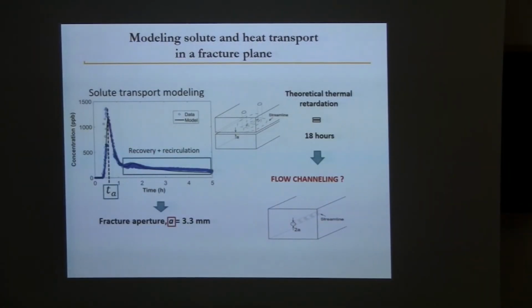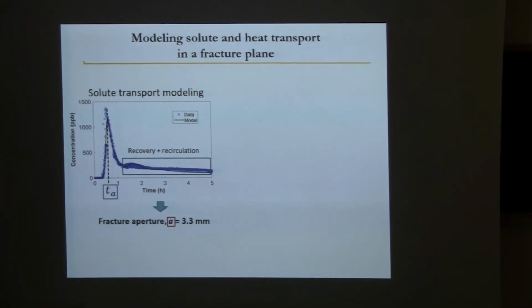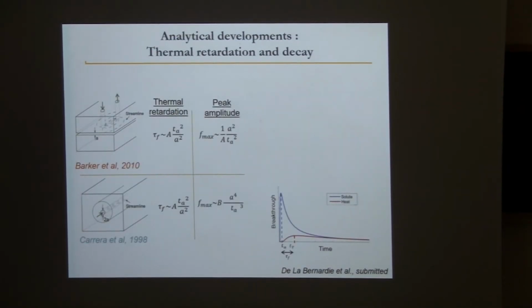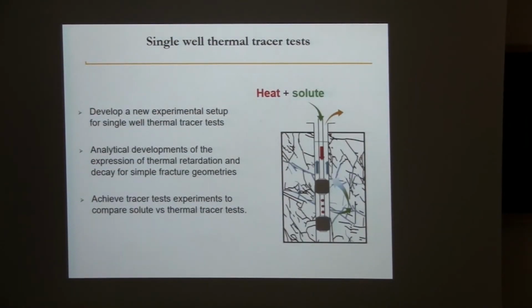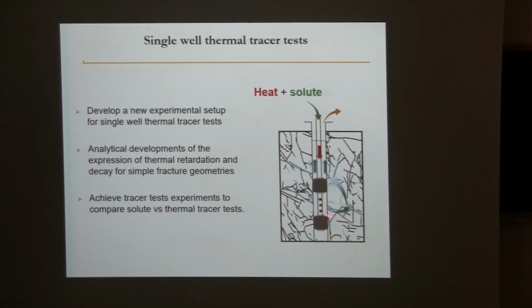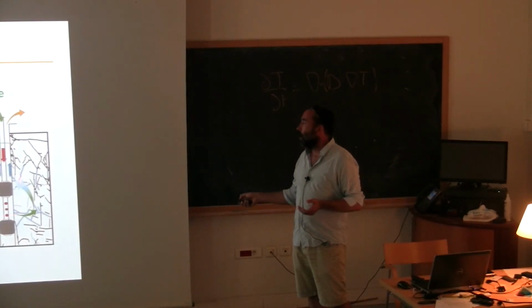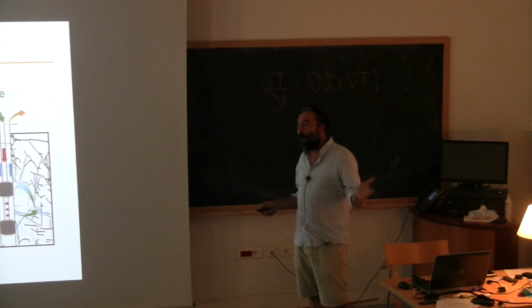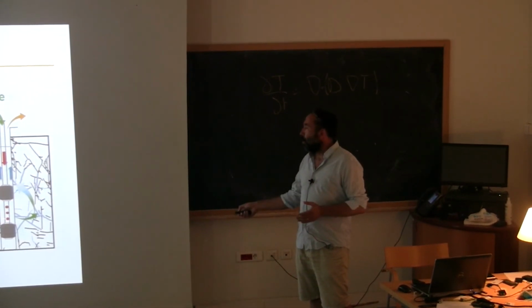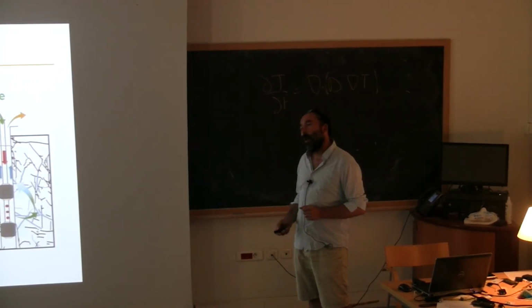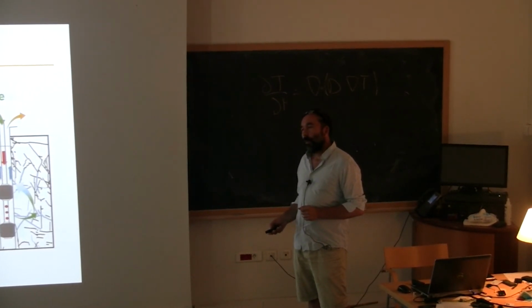So typically, the distances were short. It's about a few meters. And typically what you do before doing that experiment is that you do some solute tracer just to make sure that you are well connected. For instance, for this one, we had already done some tracer test experiment, and we knew that the tracer would take typically half an hour, 1 hour to go from here with this pumping rate to this pumping rate, and after we did some thermal tracer test.